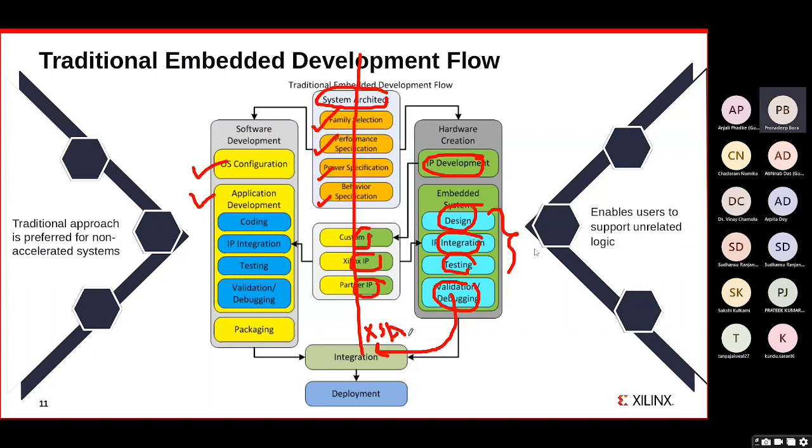So it will have all the hardware things that are required. I guess you know about memory mapped IO and IO mapped IO. There are two ways to communicate with a peripheral or a slave device. How to address it, because the ARM processor should know, right? If there is a UART protocol inside an FPGA, the ARM processor should know its address.